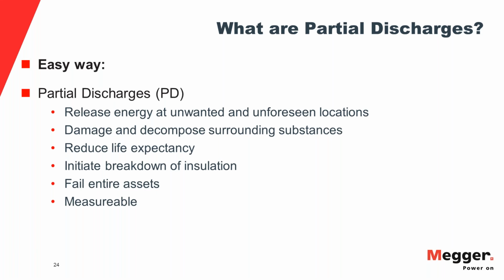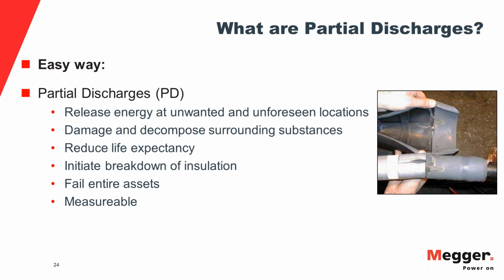Typically, back in the days, people had spare transformers right there, and they were able in a fairly short amount of time to install a new transformer. Typically, that is not the case anymore. All these spare transformers have been eliminated for commercial reasons. And very important, I just want to point this out, it's kind of duh, but of course, PD are measurable. If they weren't measurable, we would be in big trouble, but they're measurable, so you can do something with the physics of them.